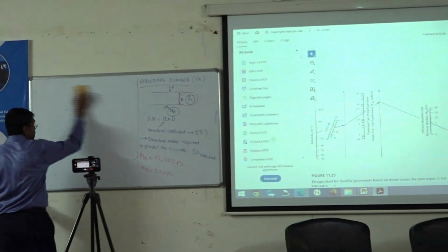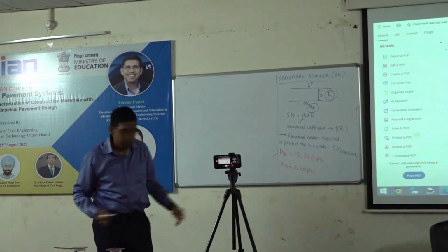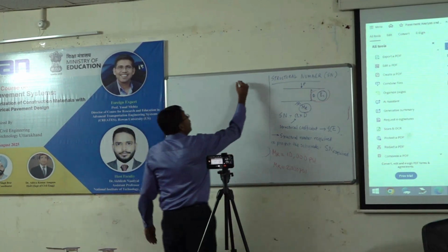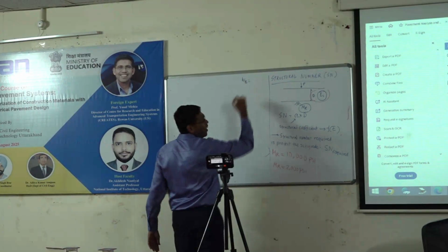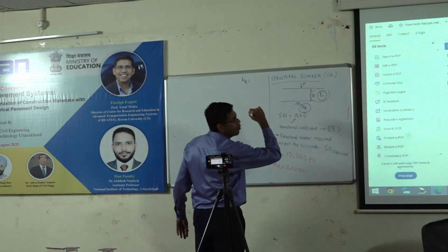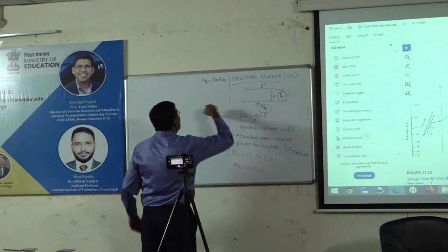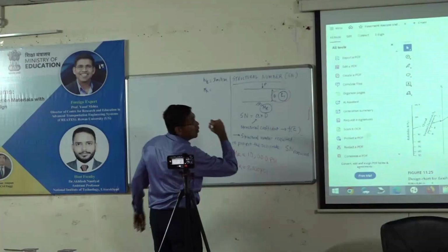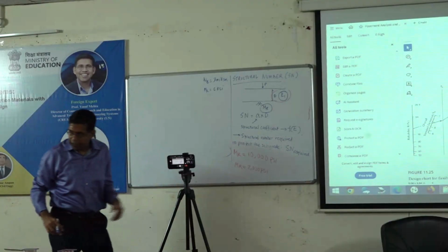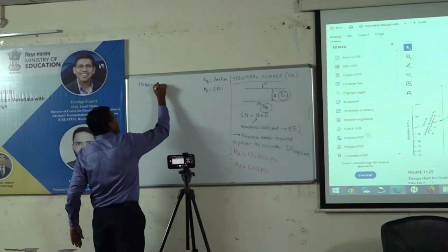Now this is the case. If I keep the properties the same as this, using these conditions, my ESAL W18 is at, what did I say, 5 million? 4 million, give or take, based on that sheet. And MR, how much? 5,000 psi, correct? Fair enough, and everything else is the same, as you can see. So now I got the SN required to protect this MR is 5.